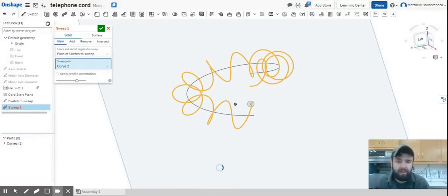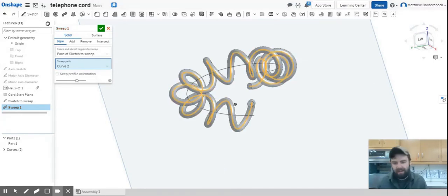In fact, you'll find a lot of times with some design, they'll intentionally leave out features that are just going to slow down the system. So if it's a type of thing where they've got a standard bolt, and as part of their design, they probably won't always include all the threads that are on that bolt. The reason they won't include all the threads is because they can just make that known with either a note within the software, or it can be in some cases assumed, but also because those threads just really bog down the system, and they're not necessary. If you're using a 1/2 inch by 13 bolt and you can just spec that out, then you just spec that out. If you include the threads, your model might be a little slower as a result.